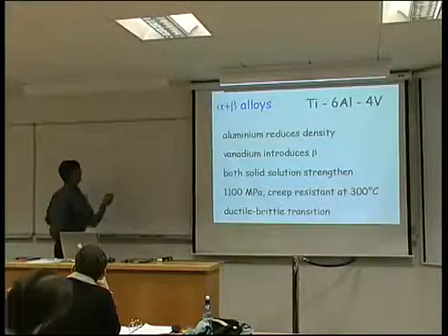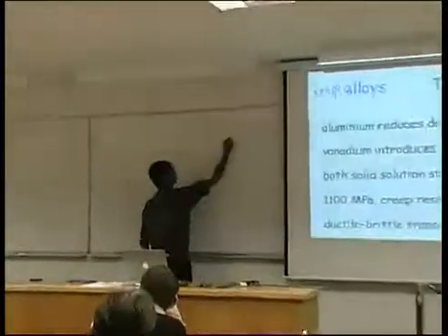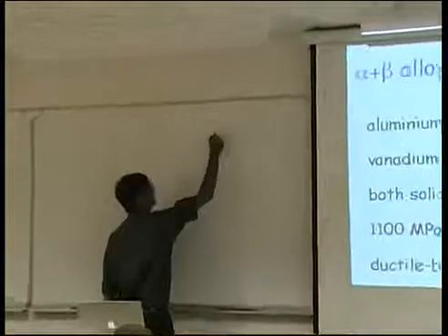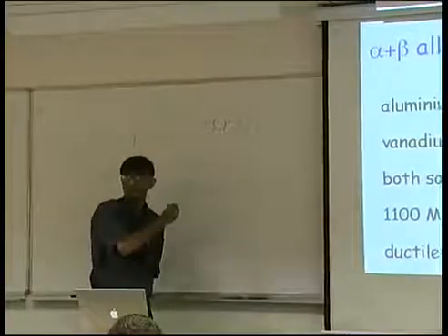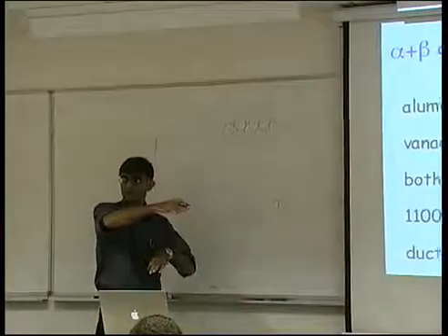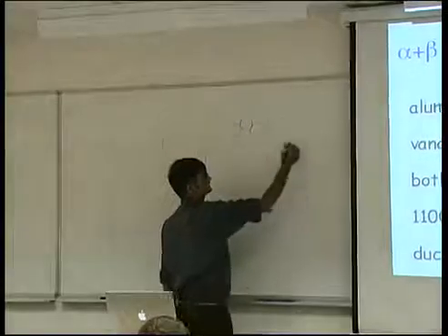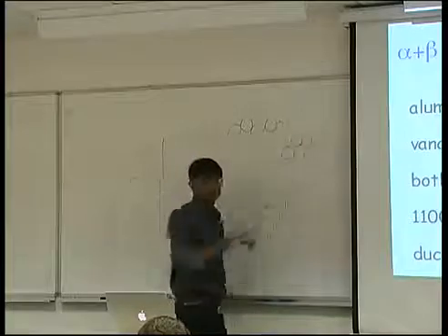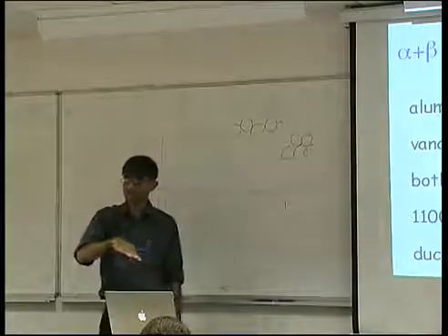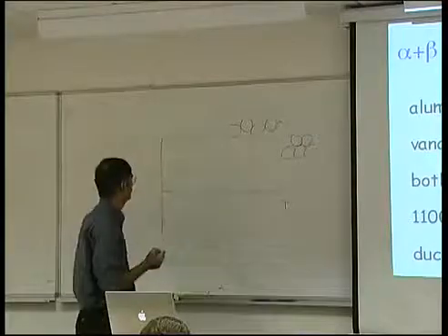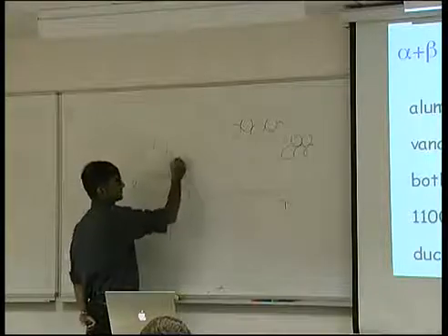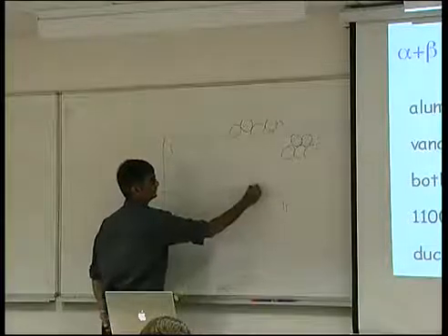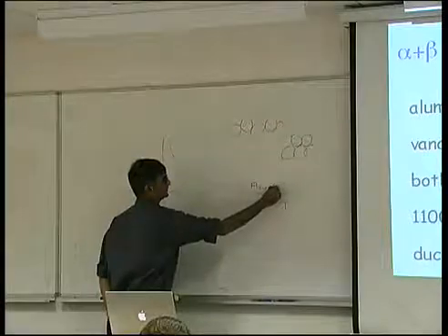Okay? Because imagine that we have atoms which are further apart, then the next layer sinks into that layer, doesn't it? And therefore to slip is difficult, whereas if they are close packed, then the depth to which the next layer is sunk into the lower layer is less. So it's easier to slip. So the flow stress is extremely temperature dependent. Okay, so this is the flow stress in a body-centered cubic metal.